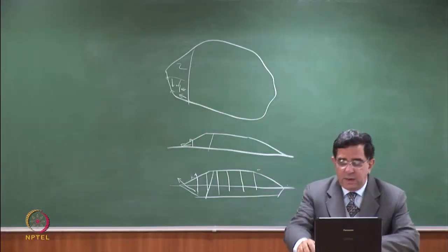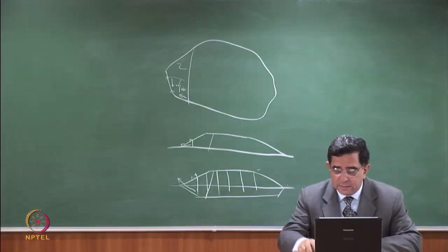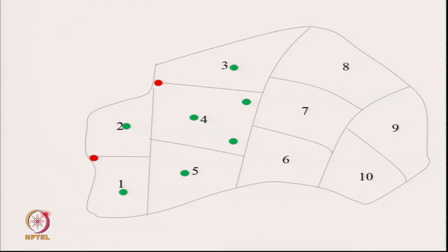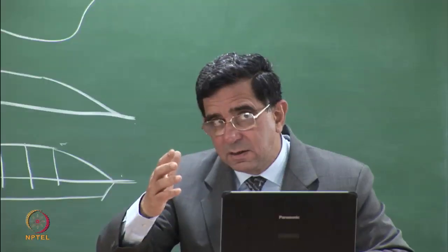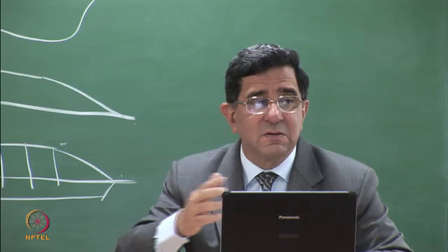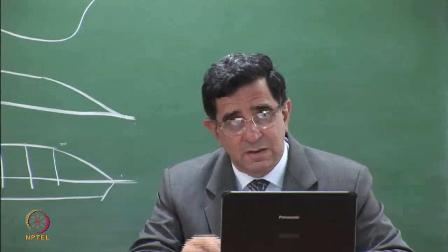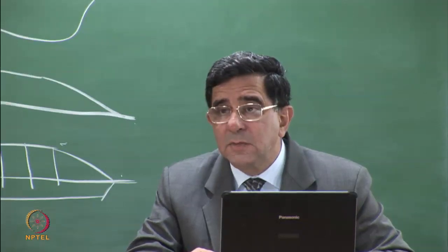So just to get a feeling of what we've done, that's where the wells may be. See, the landfill height is increasing like this, then decreasing like that. This is the area where most of the wells are going to be. Okay, so you do see that 1 and 2 only have a single well, 3 also has, but the 4 and 7 will have many more wells at a spacing of 50 to 75 meters. Of course, this all depends on the dimensions, but I just want you to get the clear picture that the leachate wells are towards the side and the gas wells are towards the center. Agreed?